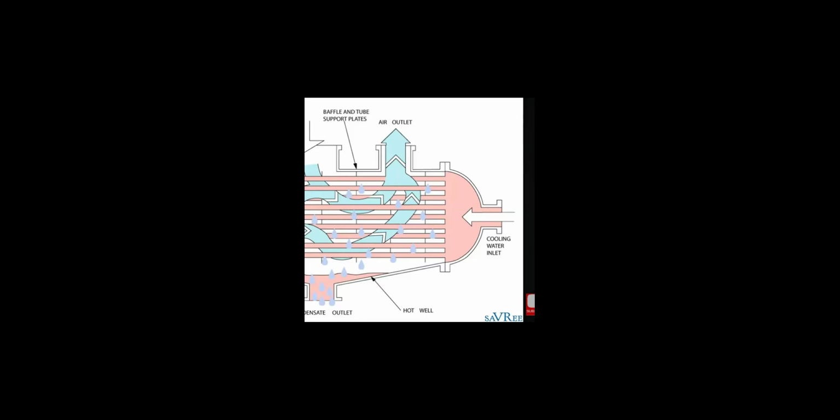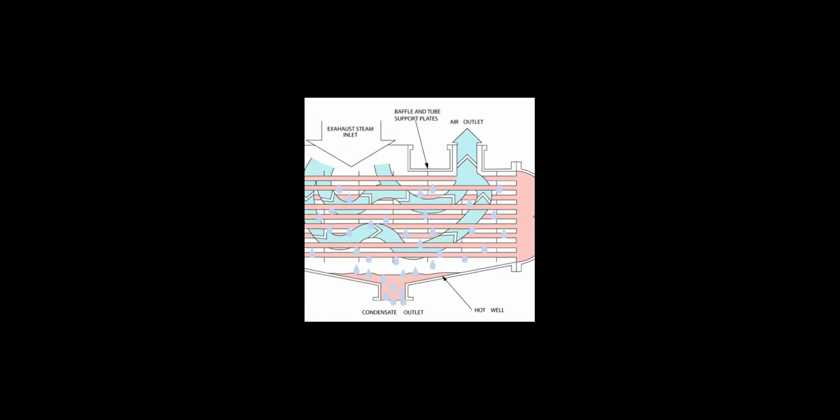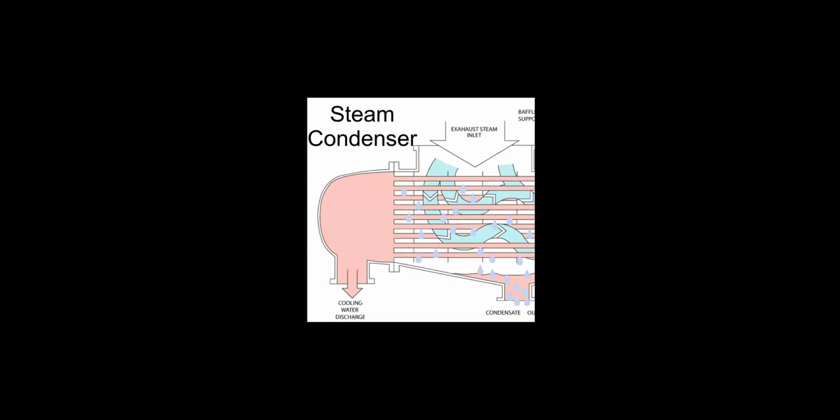Yes, thermal expansion. So in a tube type cooler, what arrangement is given for tube expansion? Sir, expandable tube stacks. Yeah, exactly. They are expandable tube stacks, capable of expanding in the axial direction. Yes, exactly. One end is fixed and one end will be free. That is why a little bit of clearance will be given there.